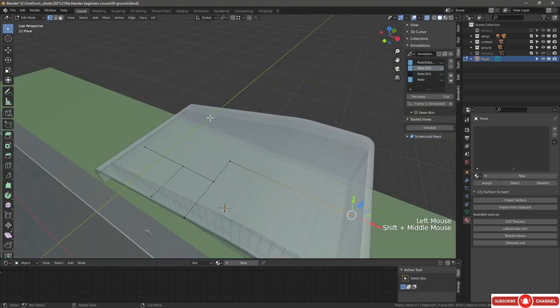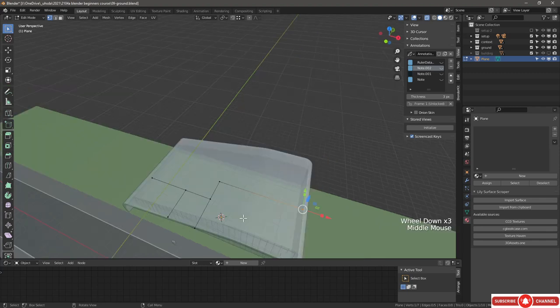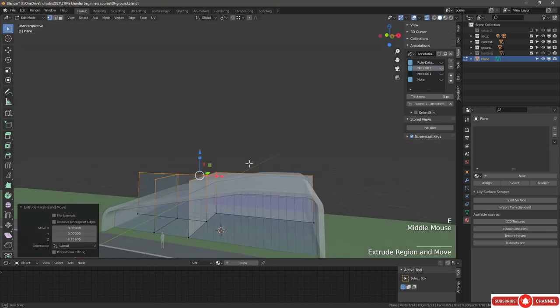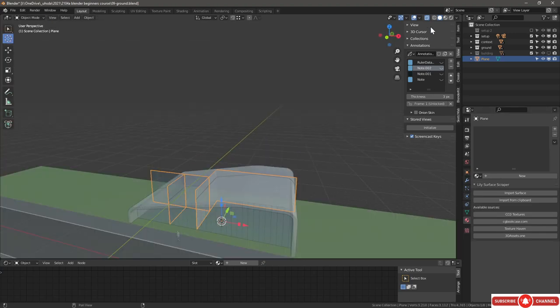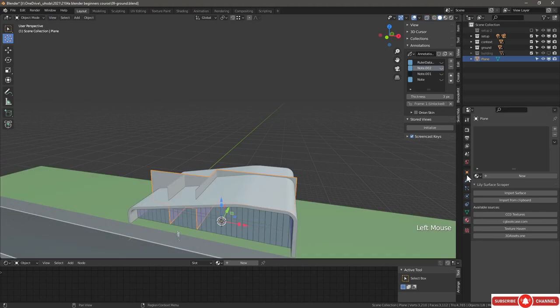So we can go further and define the interior walls, but at this point, because we're more concerned about how the image of our concept looks instead of showing floor plans, we won't worry about modeling what we don't see in our views. Let's select everything, A, and then E for extrude and Z. If we want to go beyond our boundaries, because we use Boolean in the same way that we used for the curtain wall. So now go into object mode, let's disable X-ray.